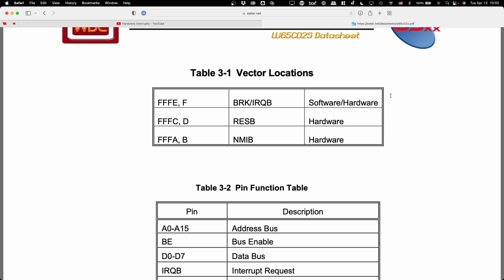Yes and no. It could be very slow in the sense that you're dedicating a large portion of your execution time to some other thing. But you have to remember, of course, that if we were to clock this processor for real at 1 megahertz, then that probably won't matter. Given the hardware on board the breadboard project, other than the processor, we have the screen and some buttons. 1 megahertz is overkill for this kind of thing. But the processor can operate that fast, so we might as well do it.